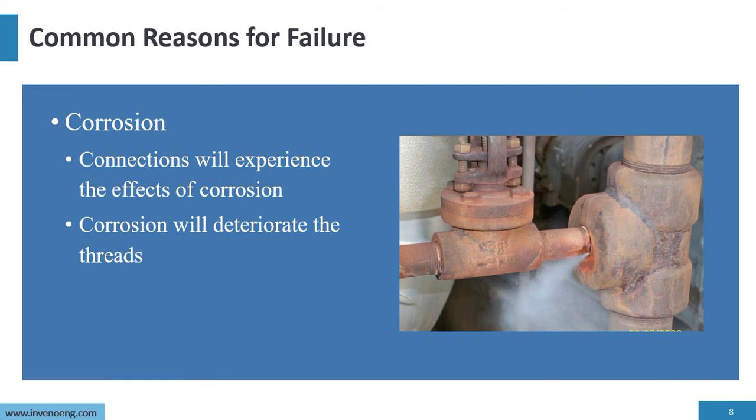Understand the different corrosions. The weakest part of the piping system is going to be the threaded connection because of the lost material. It doesn't have much resistance to CO2 corrosion. Therefore, the number one leak in the system is always an NPT connection. So if you did a leakage study, NPT connections will probably be number one.